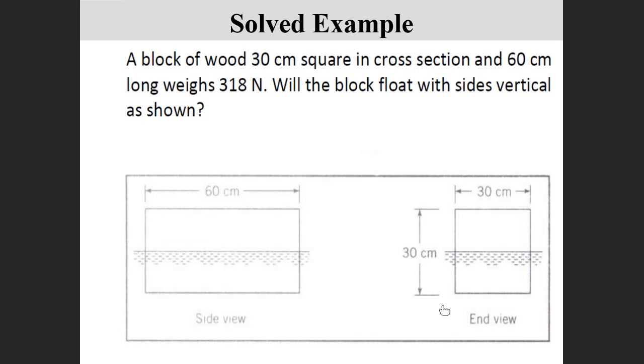Now, what he's asking is, can this floating body be stable or unstable? That is his question. The most important point that is missing from us is this distance. The body is floating, but how deep is it going into the water? Half, one third?